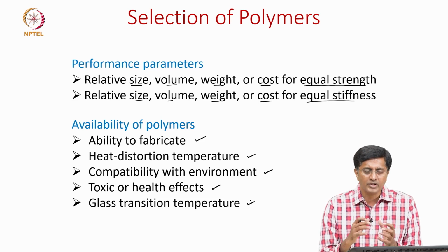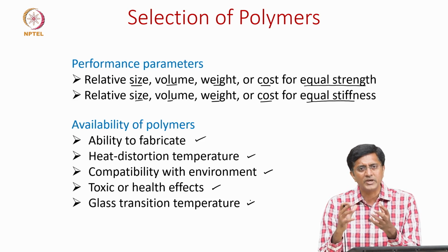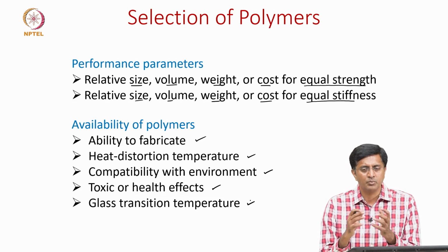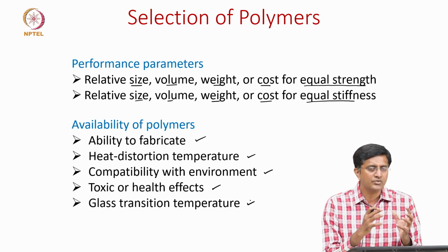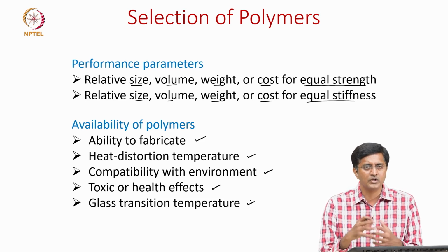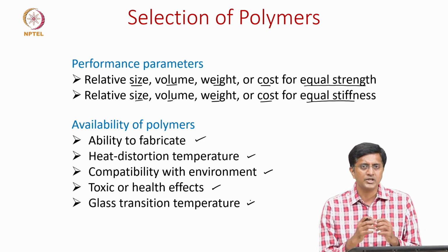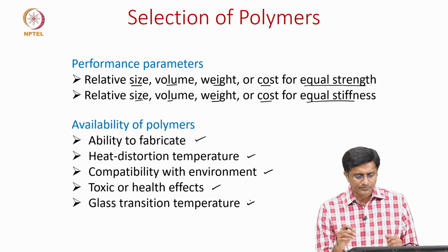But if our operating temperatures are coming close to the glass transition, that is when the material becomes softened. So, if we are looking at a stiff and hard material, maybe we want to avoid these temperatures, because then we lose the structural integrity of that component. So, glass transition temperature helps us to make the decisions in a more rational way.